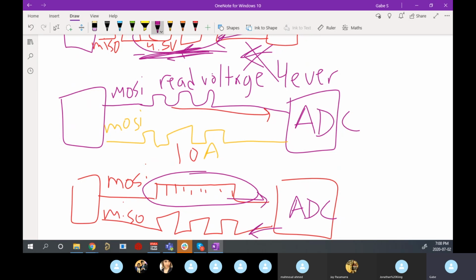And this is a property of SPI. The master will control all data transmission. It will decide if MISO is activated to send stuff back or not. For your slave to send data back, very first thing, chip select has to be activated, right? And then MOSI needs to be sending some data bursts so that MISO can send stuff back as well, whether MOSI is garbage or not.